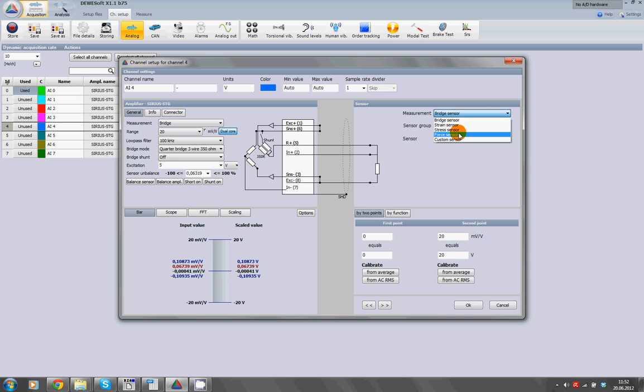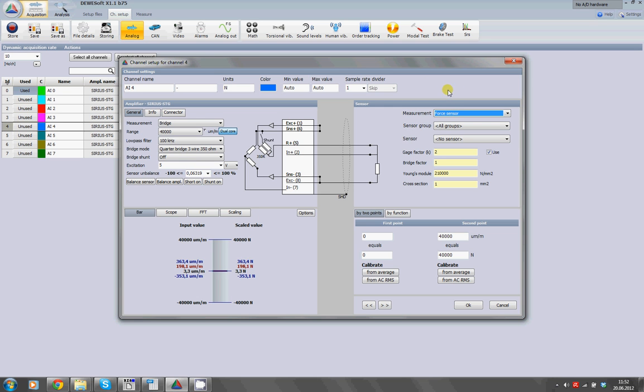So going back to a force sensor, for example, we need to enter a few more values and directly end up with Newton. So these are additional features. If there is a TEDS connected, it will automatically give you the button here, write to TEDS. So all the changes, all the information in here can be written back to the TEDS sensor.